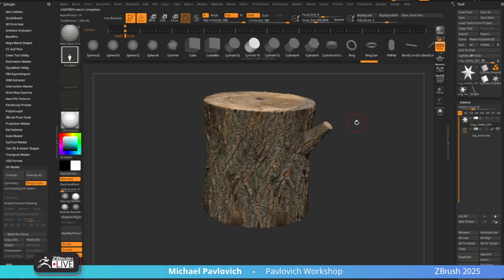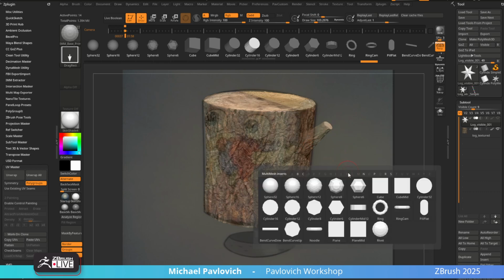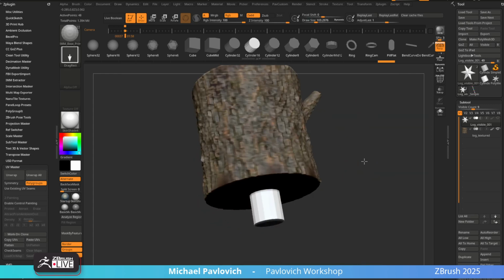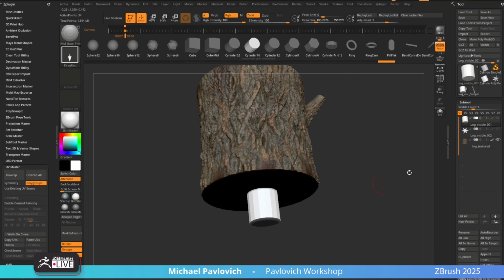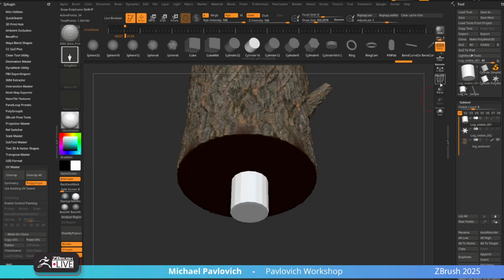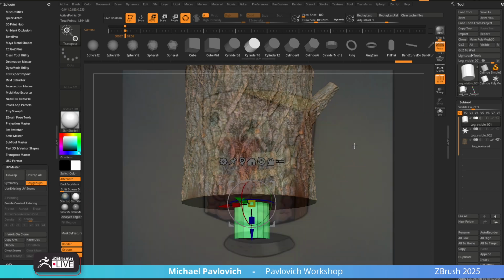So now we can use our left and right arrow keys to snap back. We can do Shift Z to turn that reference back on. So if I move this, again, just arrow keys to snap this back to where it should go. Now, again, Alt E M, go grab Cylinder 16, go to the bottom here. We have X symmetry turned on. I'm going to drop this on. We're going to say Split Mass Points, and we'll switch here. I'll keep this on here because we'll do Polyframe. And again, hit W, Shift Z.